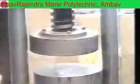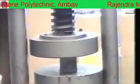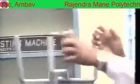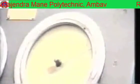Test the specimen in the compressive testing machine by placing the cube in between the platens of the testing machine. Apply the load at a uniform rate. Note down the load taken by the sample at its total failure. The load taken by the cube divided by the area of the face of the cube which is in contact with the platens of the compressive testing machine will be the compressive strength of the cement.